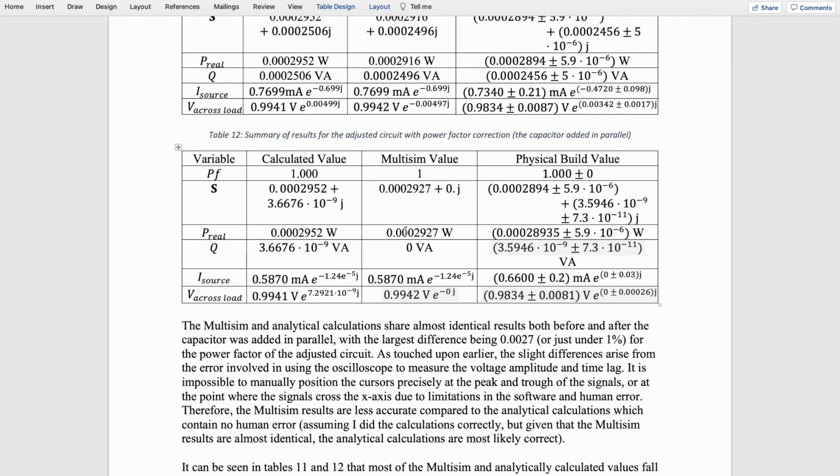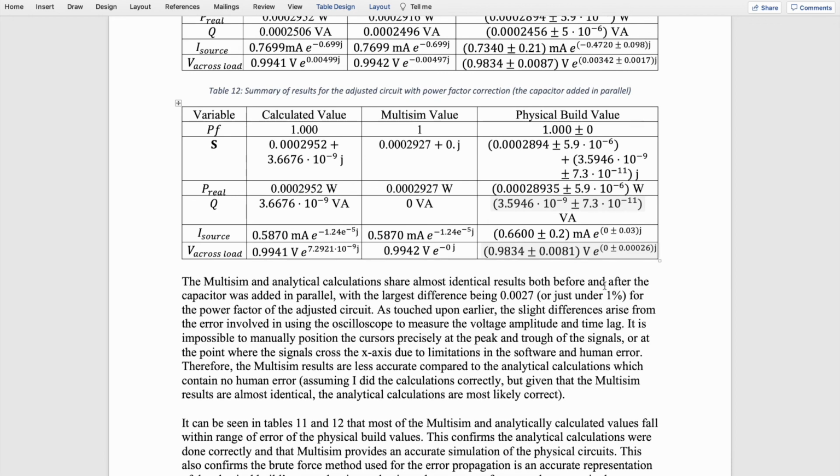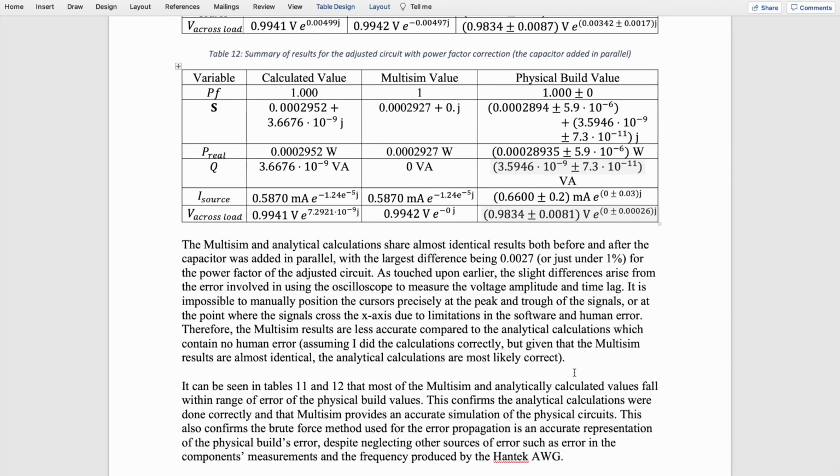And this also corrected the out of phase current and voltage. As we can see right here, they were out of phase, whereas now they're approximately 0, I mean, really small numbers. This is exactly what we want. We want that current and voltage to be in phase so that the load network is constantly dissipating power.